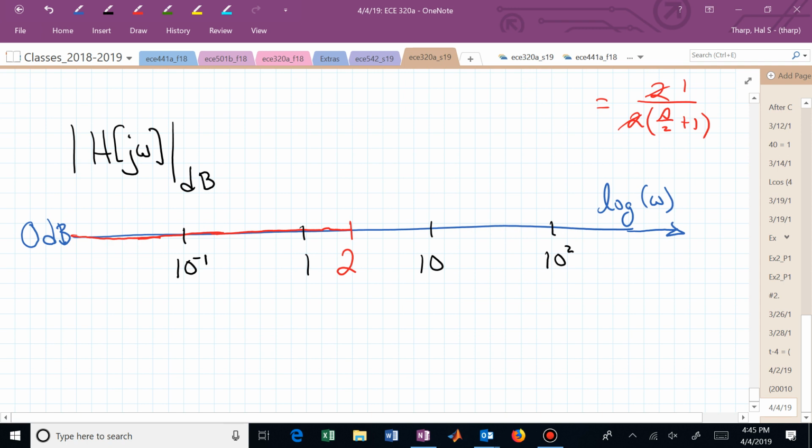We're up at j2. And I look back at that pole, and I do have exactly the same vertical distance as horizontal distance. We said, okay, now's where we say the imaginary part is starting to influence the magnitude. And now we just roll off at 20 dB per decade.